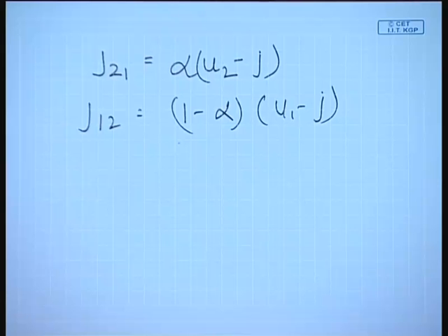So, these are the definitions which I wanted to say. Volume flux I have already told you, and after that it is the drift velocity, which is the component velocity minus the average velocity, and then the drift flux, which we have defined as the volumetric flux of either component relative to a surface moving at the average velocity. Now, remember one thing, this drift flux is very important. In fact, we will be developing a drift flux model using this particular concept.